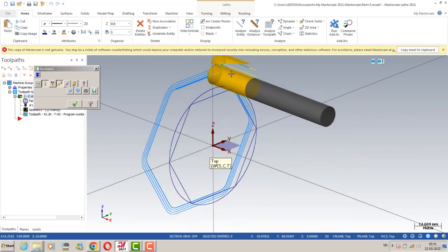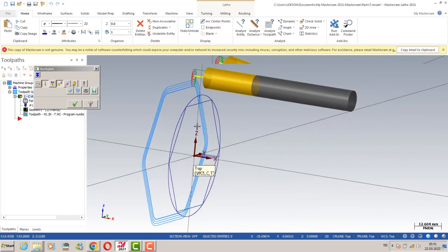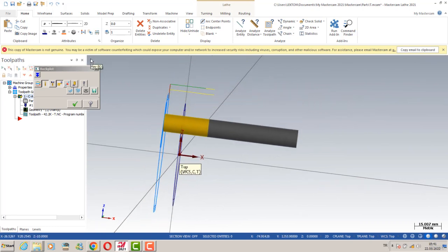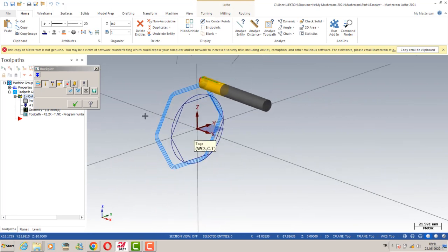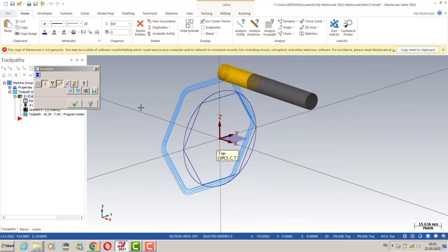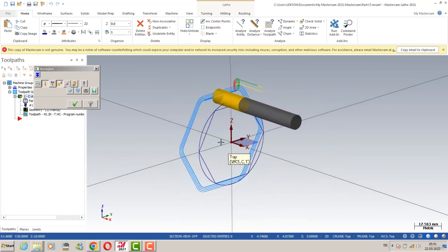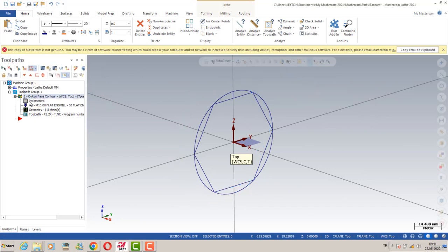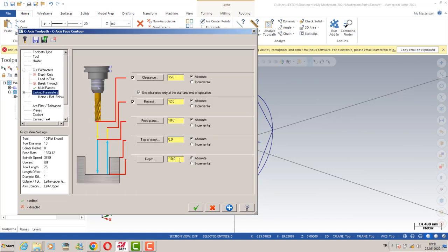So that's a better way to create better surface options, I think. So this is the multi-axis options for our process. Okay, and this is my opinion. Of course, if you intend to create that kind of toolpath, I prefer to use that kind of parameters, according to the length of your tool helix. You can write different options here. Of course, maybe that can be 50 millimeters, so that's not enough for my tool helix length.